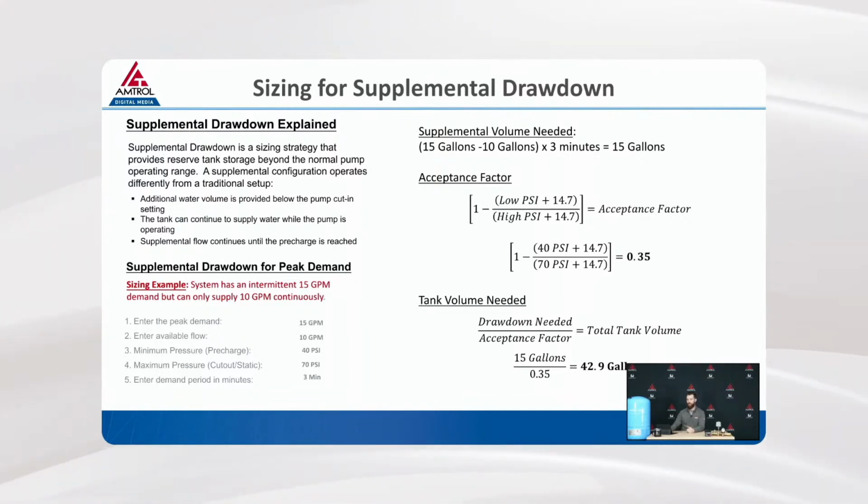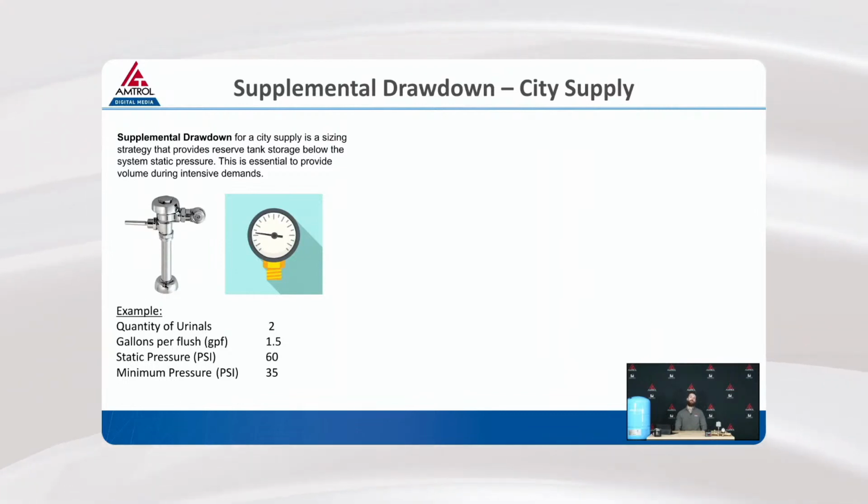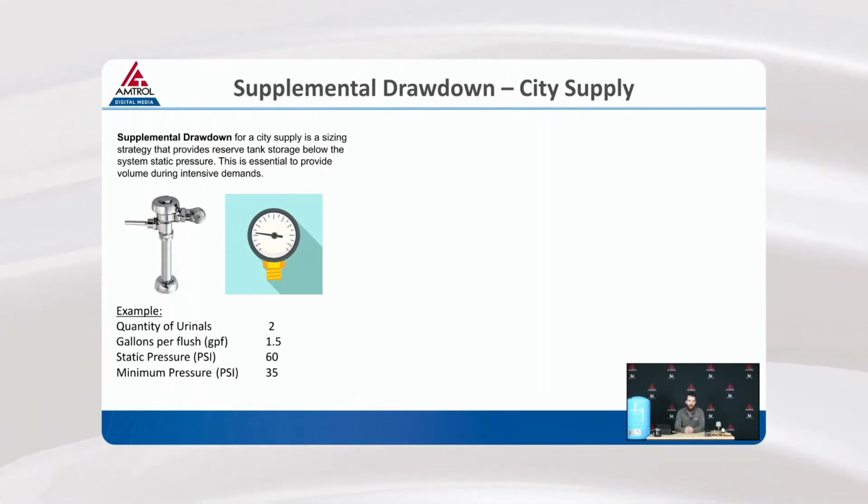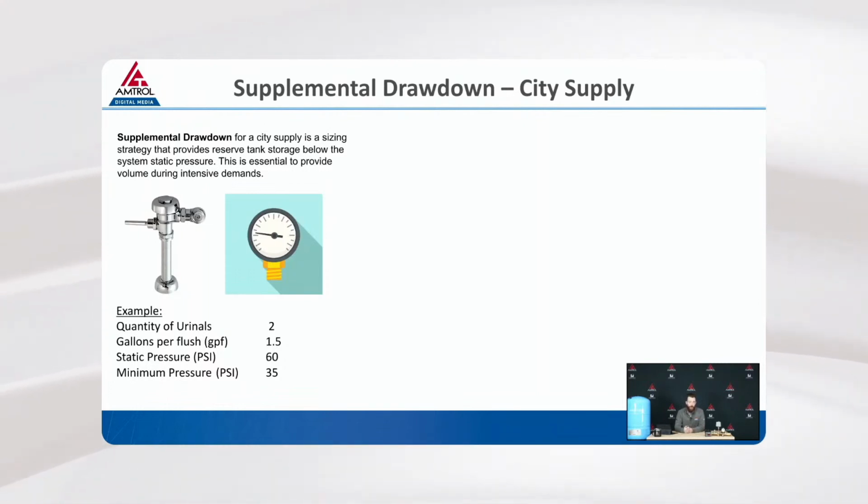So hopefully that made sense, but I want to jump into another scenario here with maybe a smaller tank, or something more common we see: flush valves. Very, very popular scenario. You have Sloan valves, flushometers, all those different tankless flushing devices out there. A lot of times, unfortunately, you run a really small half-inch pipe to these things and you flush 3 at a time and there's absolutely no water. They don't flush. Very, very common problem out there as builders, but we have a solution for it.